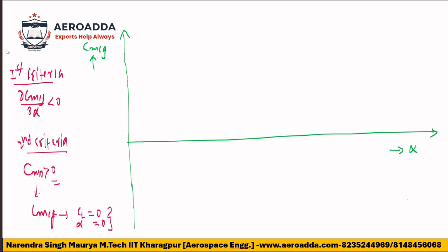Right. Coming to the main graph, this is very important, I would say. Please concentrate. So check it now. See here, first the main contributor is nothing but the tail, which is always producing, by default, a stabilizing effect. It is contributing positive stability. Positive stability means it is going to stabilize the aircraft.